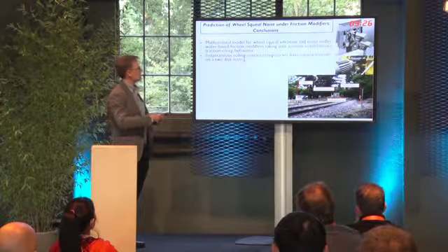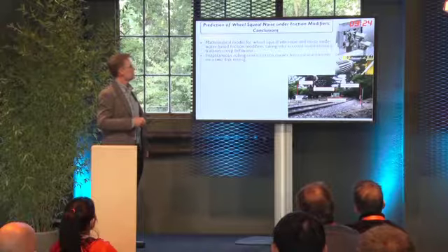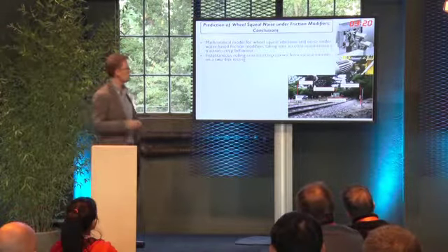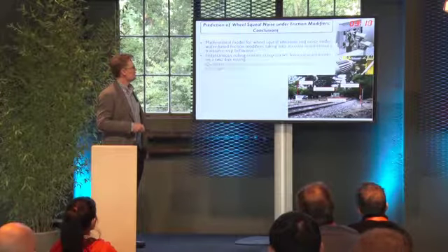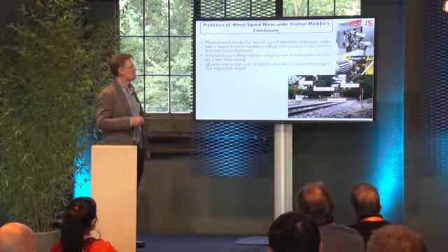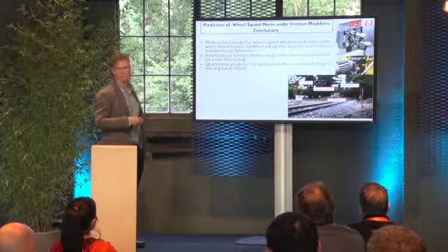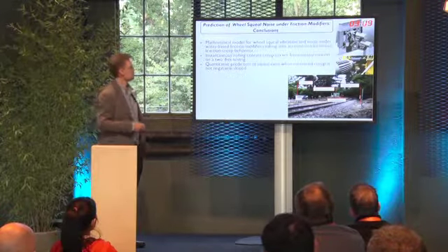So we've managed to back calculate instantaneous rolling creep curves based on our measurements of the quasi-static curves and predict the squeal even when it looks like the creep curve is not negatively sloped.